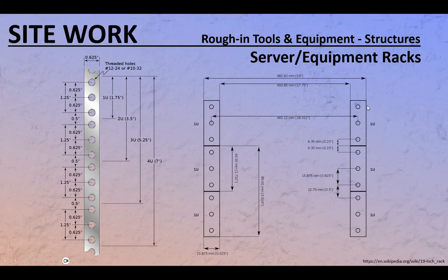Right? That's 19 inches. Then, of course, it's not like you need to know that. Just you need to know that's a 19-inch. It's a rack kind of equipment. The rack rails, they are divided into units. Each unit, rack space unit, consists of, well, what is it? 44.5 millimeters or 1.75 inches from top to the bottom. Right? And it includes 3 mounting holes.